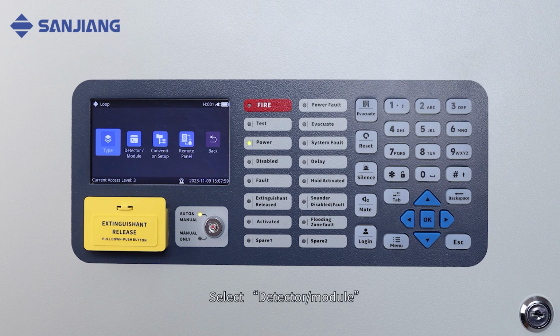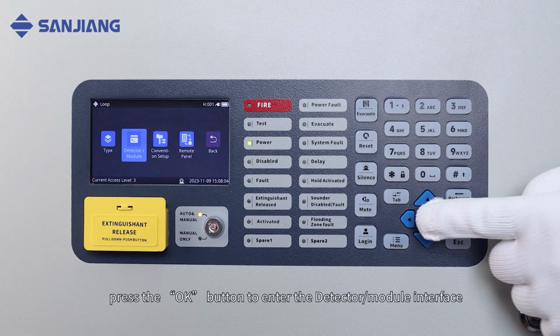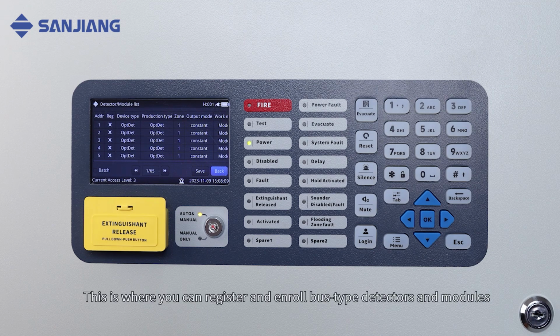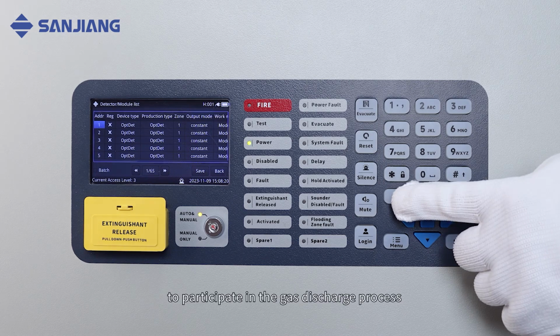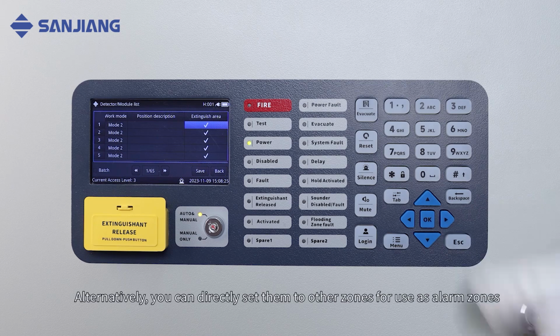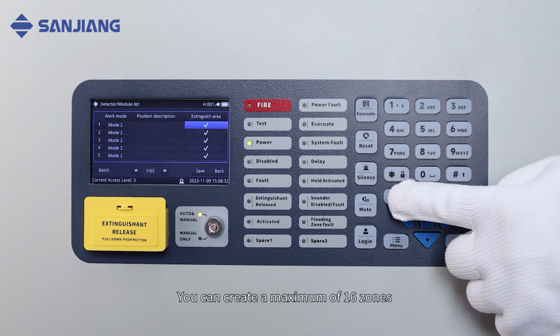Select Detector module. Press the OK button to enter the detector module interface. This is where you can register and enroll bus type detectors and modules. You can add the registered detectors to the gas discharge area to participate in the gas discharge process. Alternatively, you can directly set them to other zones for use as alarm zones. You can create a maximum of 16 zones.